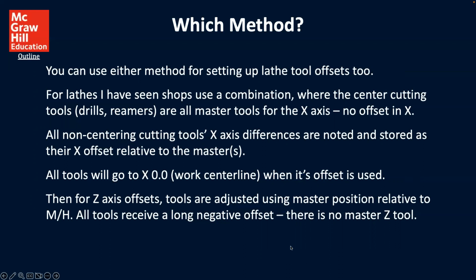Then for Z-axis offset, tools are adjusted using master position relative to machine home. All tools receive a long negative offset. There is no master Z tool.